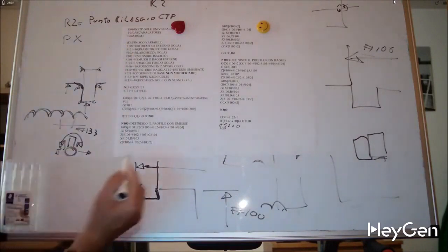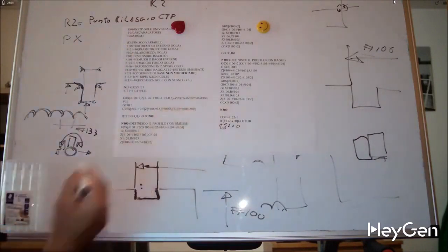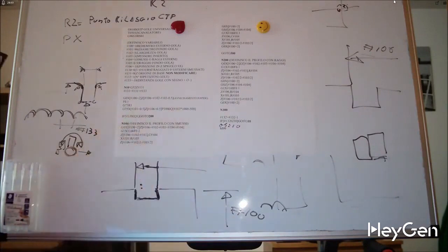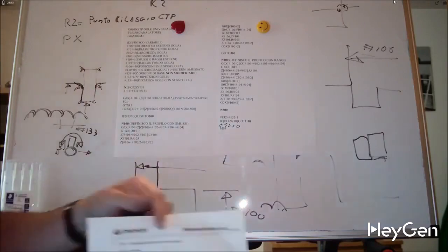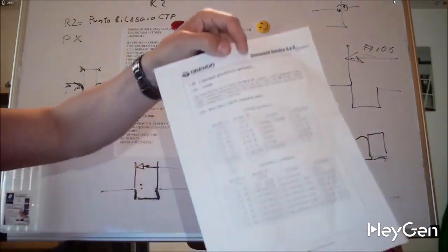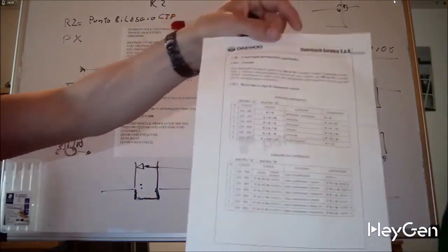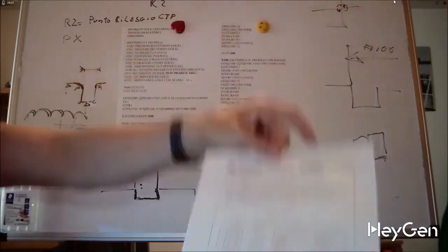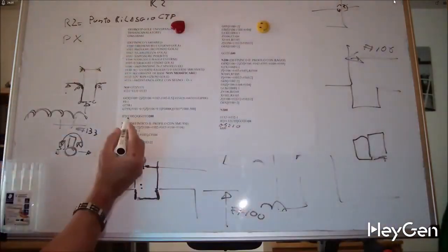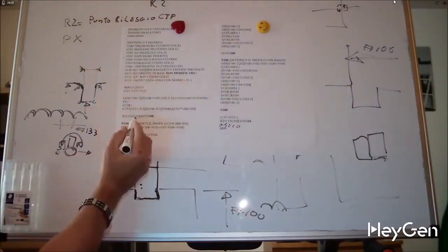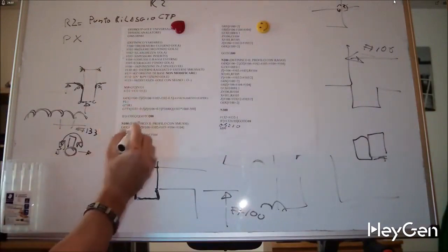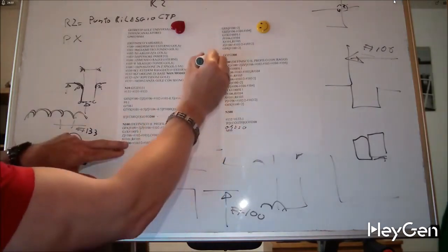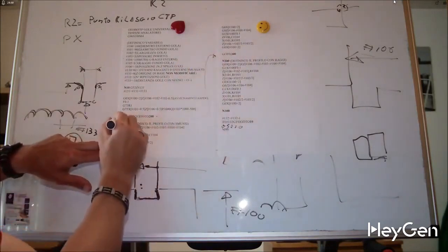So from the moment you insert the thickness of the insert, Q will automatically adjust. If #130, Q, according to the table I gave you. What I showed you earlier, just wait, okay? I showed it to you before. Go back in the video and print it out. So, if EQ is an equality, if #130 equals 0, I go to N200, so I go here. If it's not equal to 0, I continue.